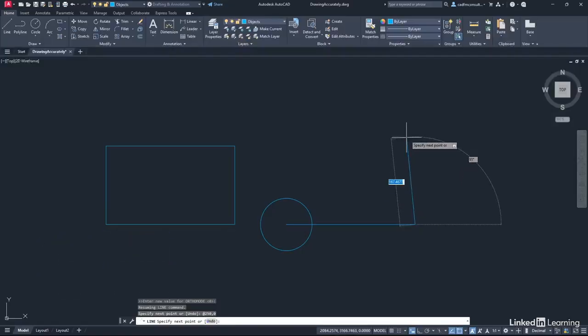I now need to go vertically. So the X value will be 0. Again, I type @, and AutoCAD goes, oh, you're typing in a coordinate. So the X value will be 0. And then we type the comma again. Notice I've kind of hit the comma twice there. Make sure that comma disappears in that box there. I've just backspaced it. So it's 0. And then we need to go upwards. So Y is positive 150. I then press enter to confirm. And there's our vertical line.